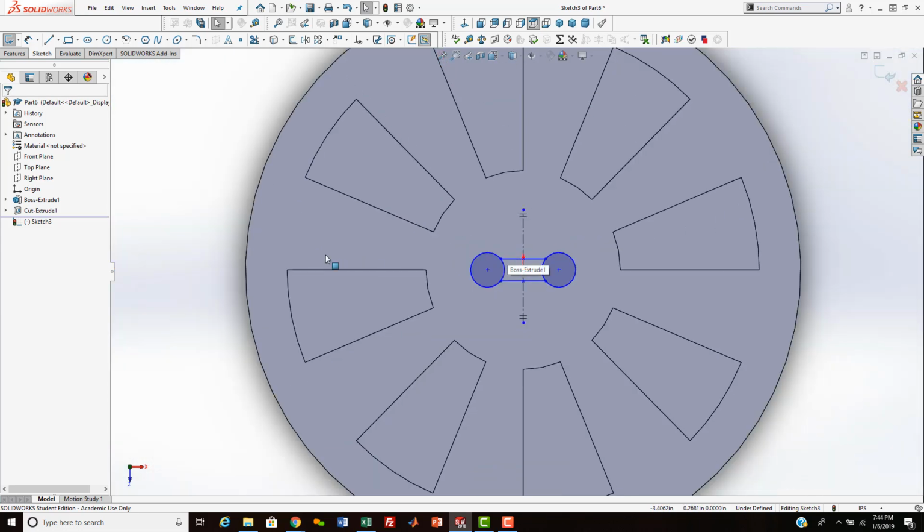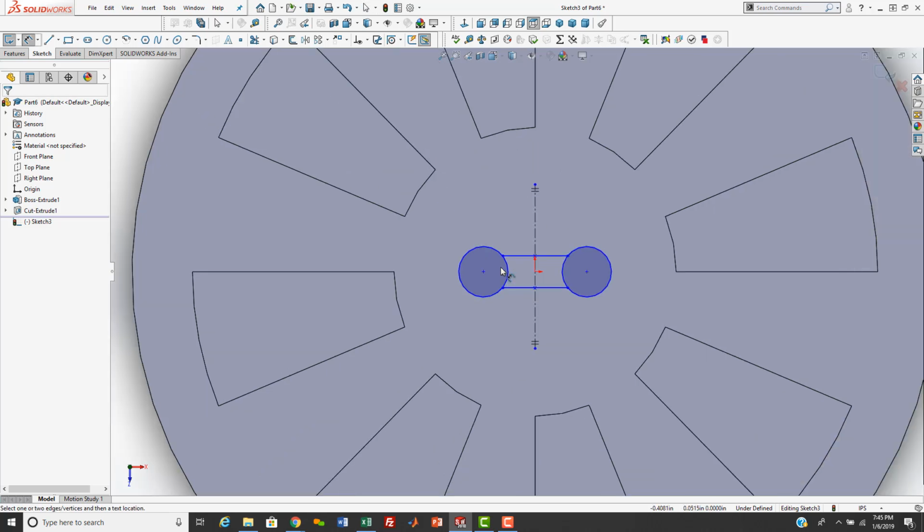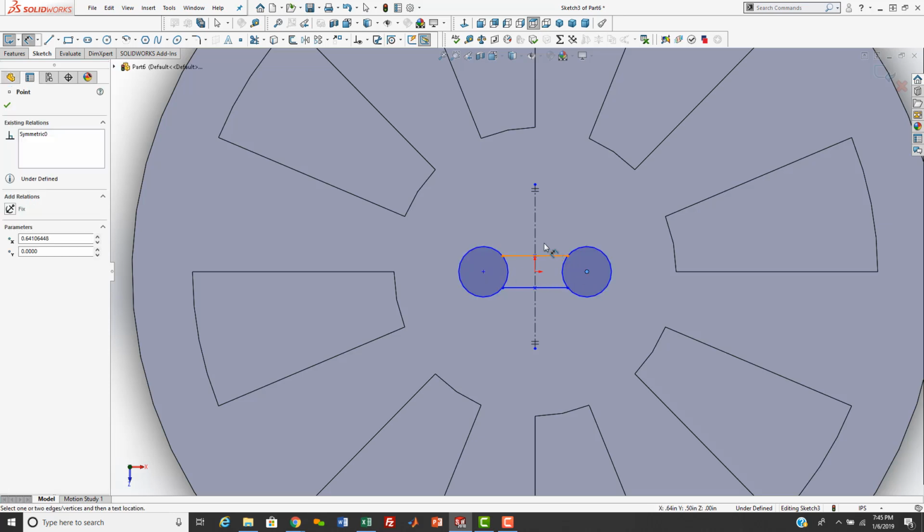Now another way to get dimensions. I've shown you two. One was to come up here and select it off the toolbar. Second was to hit the S and get that. A third way to do it is to hold the right mouse and slide your mouse upwards, and that'll bring you to the dimensioning tool. How cool is that? Yeah, that was far out.